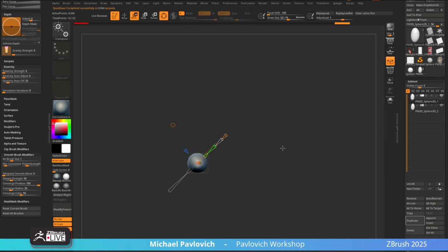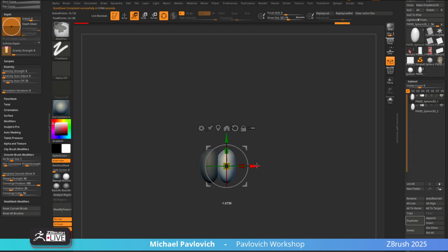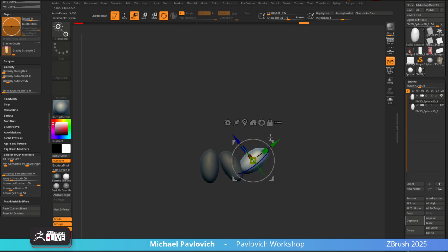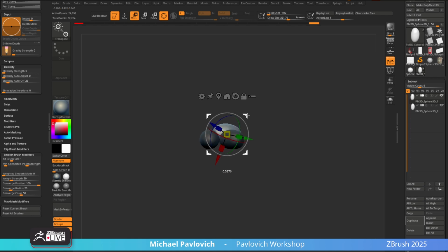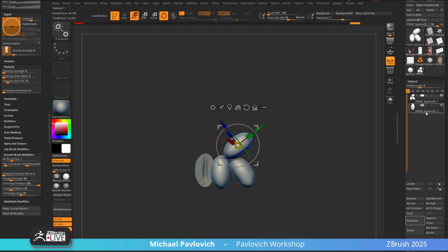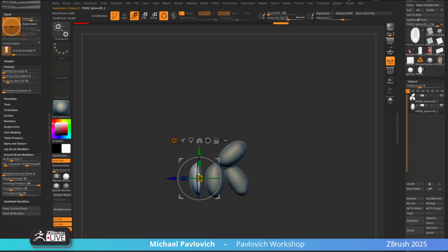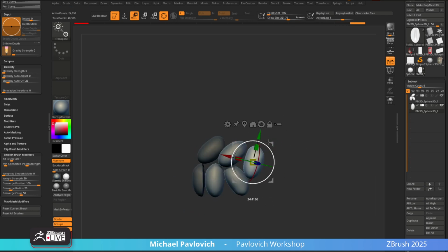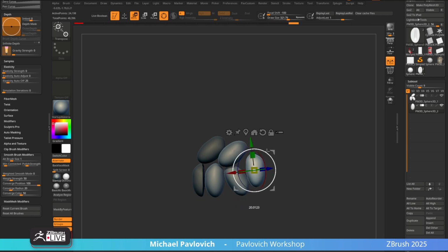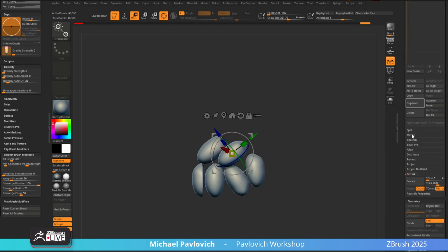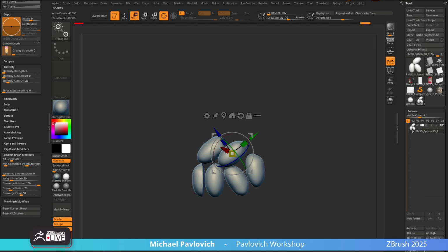Let's go ahead and just distribute these peanuts. So hit W. I'm going to hold down Control and drag out a copy, and we'll rotate it around a little bit so it's a little different, and then rotate a copy and maybe go this way, and this one will lean up a little bit here. Then for this one, we'll hit W and move all these over. And then we got a little half shell peanut. This one we'll turn to the side, Control drag. We'll turn this one to the back, Control drag. Again, even on this one, we'll tilt this one up. Then I'm going to take all of these and merge them down. My hotkey for merge down is, I don't remember, Control E. You can go to here and just hit Merge Down. So now this is all one subtool.